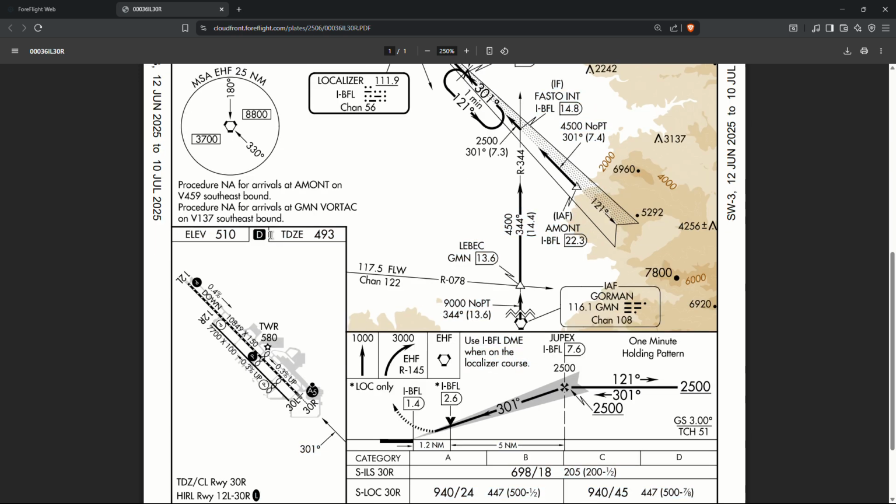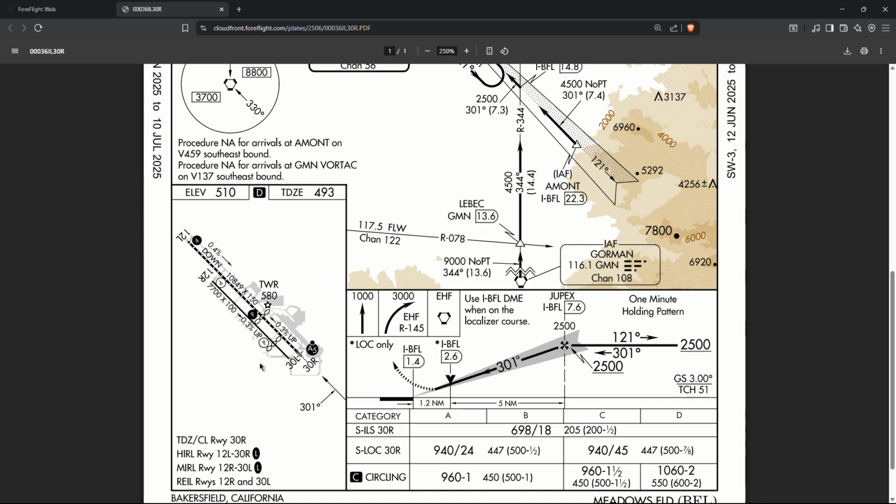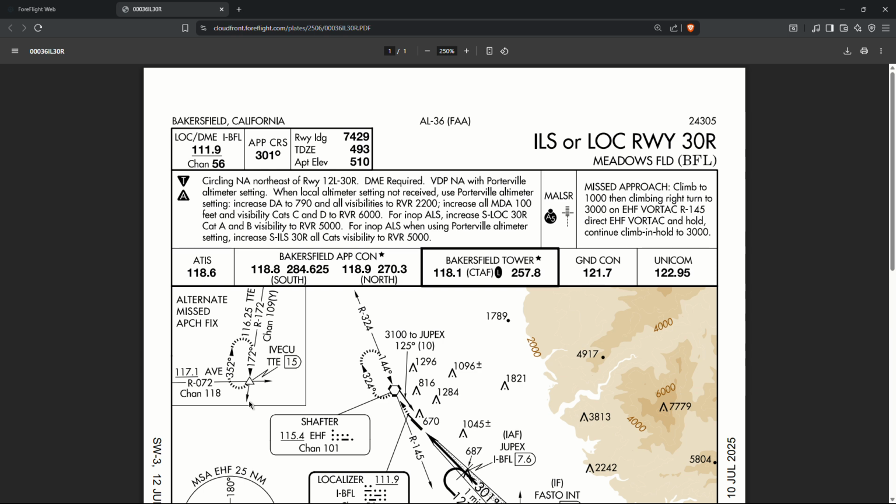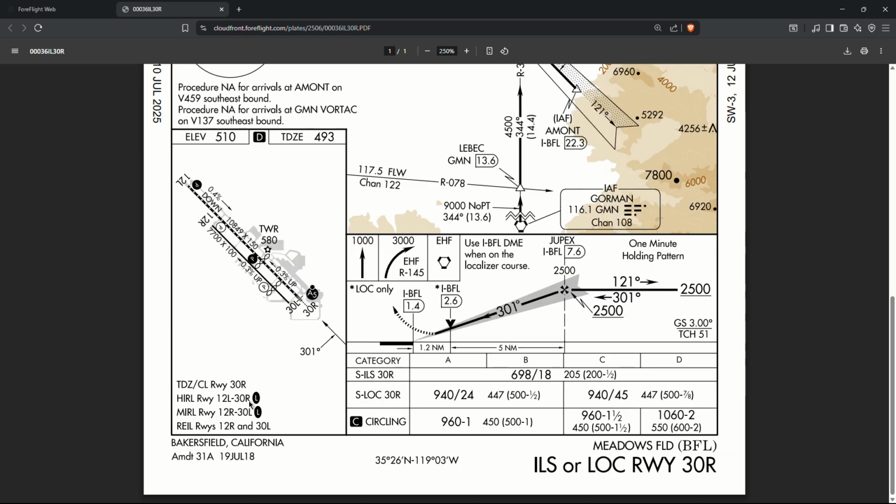Going down, again, we get the elevation, touchdown zone, a lot of information about the airport. Again, see that slight slope of 0.3 degrees up. We have different markings, the approach lighting, where the tower is, the length of our runways. More information as well, and all this is going to be listed on the Digital Terminal Procedures Supplemental. It's a great resource. There is so much to know about instrument flight, so that's always a great tool to have. And again, the AIM as well will tell you a lot that you'll need to know regarding each of the systems, because we have VOR approaches, ILS approaches, localizer approaches, all those different types of approaches. And that'll tell you all the information you'll need.